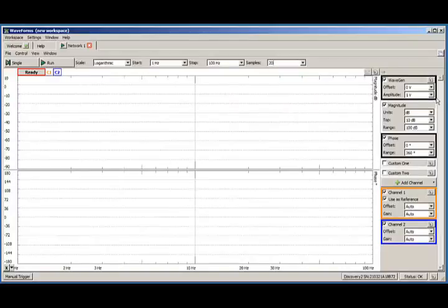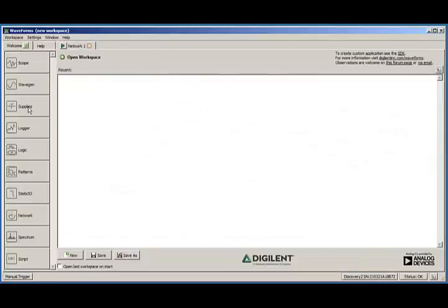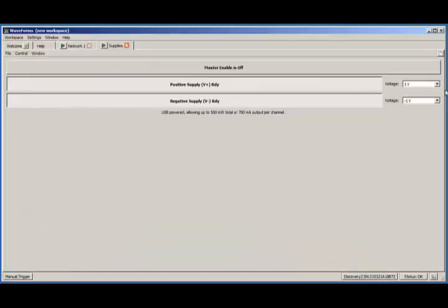The DC gain of 10 means that I can't have a very high input voltage. And I'm going to start out at 40 dB and have a range of 40 dB. My filter's active, so I need to apply power to this, so plus minus 5 volts.